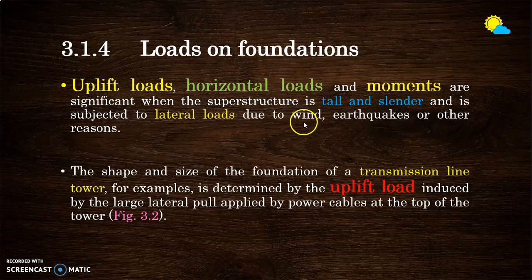They are especially dangerous and risky when you're looking at structures that are tall and slender, like high-rise buildings and typically towers. Why? Because forces like winds, earthquakes, machineries, or sudden exposure will cause lateral loads, and these loads are going to cause what? Uplift. Let's look at one example here.